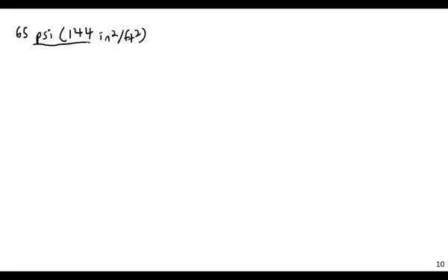If I'm going to do this all in feet, I need to use consistent units. Divided by 0.84 times 62.4 pounds per cubic foot. So basically I'm doing all this in pounds and feet. Again, this is the specific gravity, and 62.4 pounds per cubic foot is the specific weight of water.